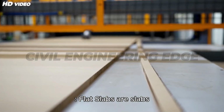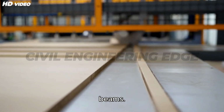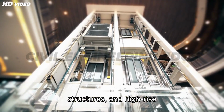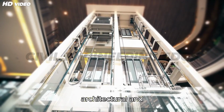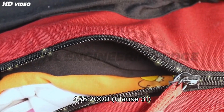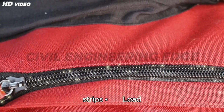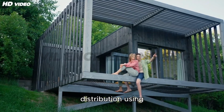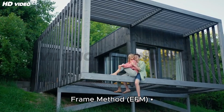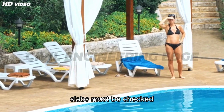Design of flat slabs. Flat slabs are slabs directly supported by columns without using beams. They are ideal for open floor plans, parking structures, and high-rise buildings due to their architectural and construction advantages. Design as per IS 456:2000 Clause 31 includes division into column strips and middle strips, load distribution using direct design method (DDM) or equivalent frame method (EFM), and special consideration for punching shear around columns.